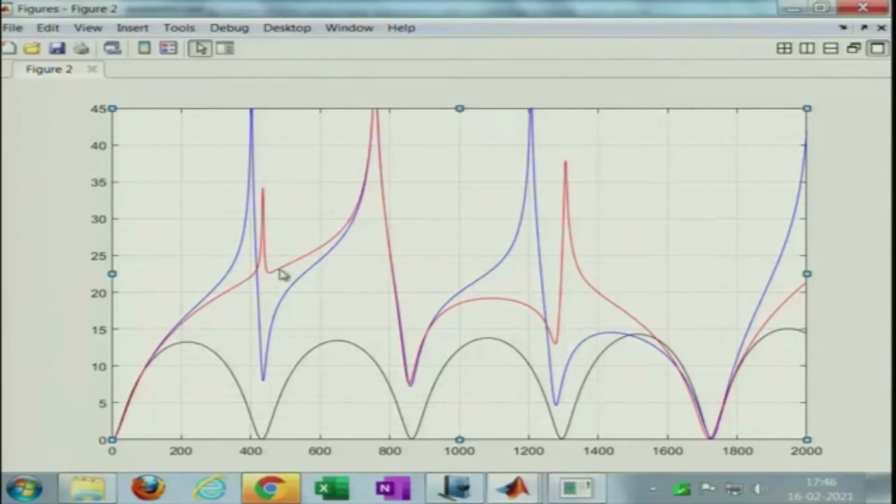So, basically it is possible to tune the extension length in such a manner that your first attenuation peak, due to the resonator formed at the inlet, cancels the trough, and you see a dramatic increase. This was only 13, now it is much more, 18.5 dB attenuation, and at the trough you are getting more than 20-25 dB attenuation. So, this is a fantastic performance.